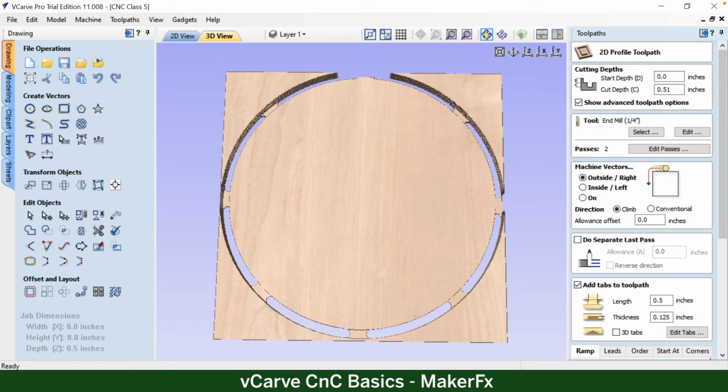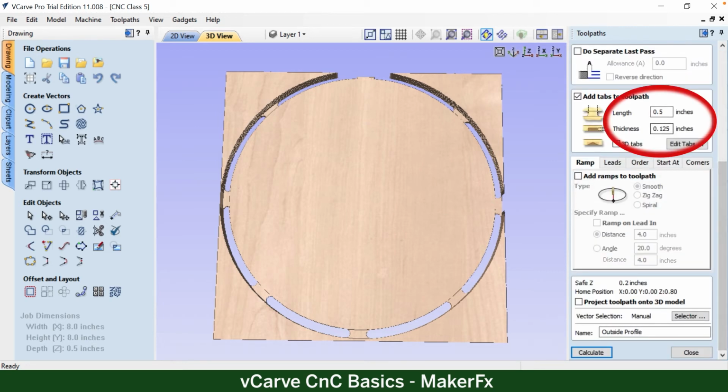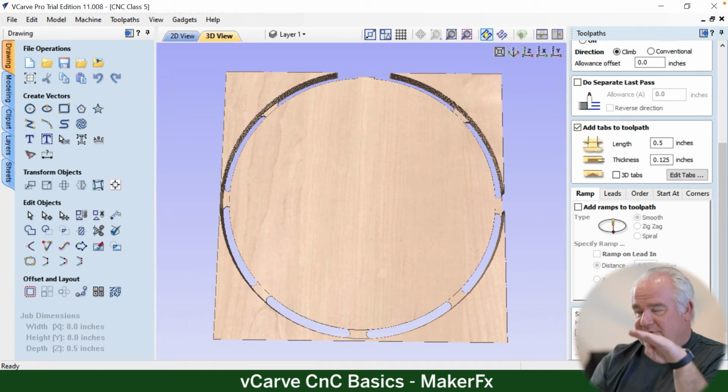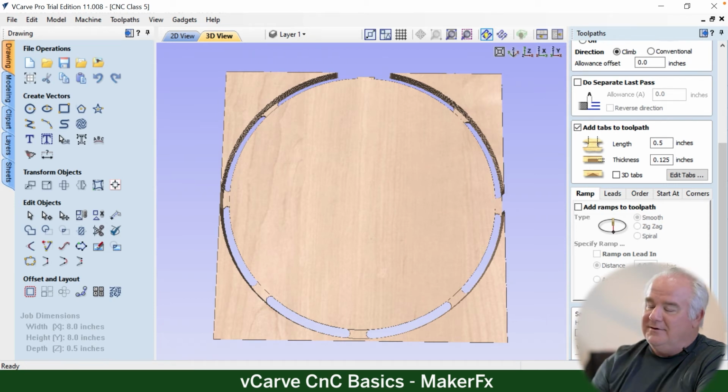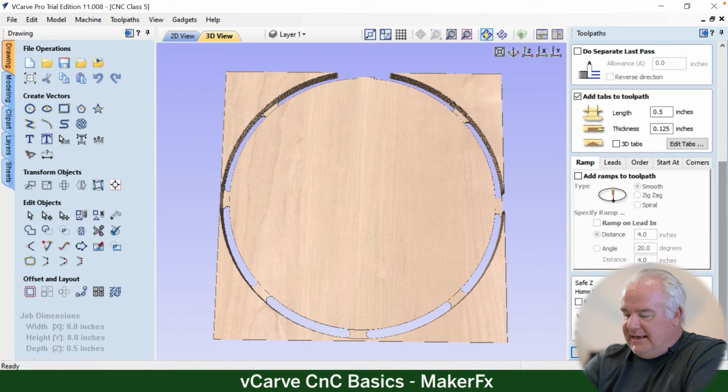If we go back into the toolpath, you can control the thickness. So this was a leftover from the last time I did it. So the thickness of those are going to be 1/8 inch. So it's a 1/2 inch material. We told it to go down. The cutting depth was 0.25, so it's going to do that. And then that second pass is where it's going to leave that to be an 1/8 inch tab. So that's how you get back in and edit a toolpath.